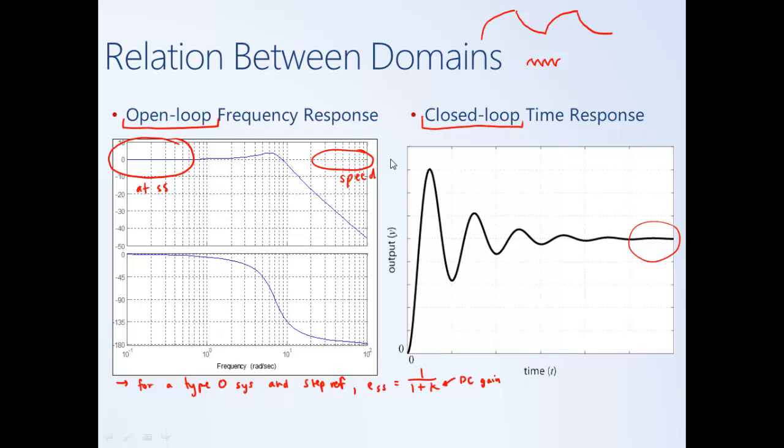Now let's think about what would relate to overshoot or oscillation. One thing that you might recognize is basically how big a system's resonance is. If it has a large resonance, that indicates that the system will have more overshoot. Furthermore, if a system overshoots a lot, it tends to indicate that it's not very stable. And so we can also look at stability margins, in particular phase margin.